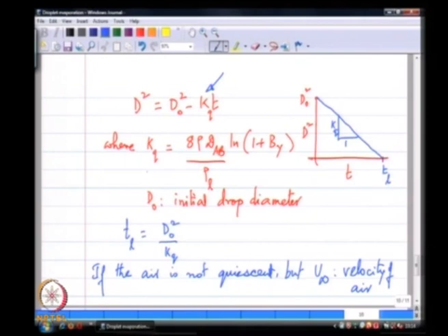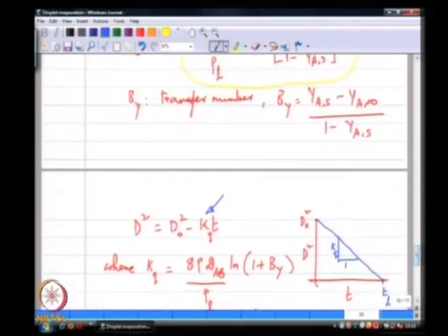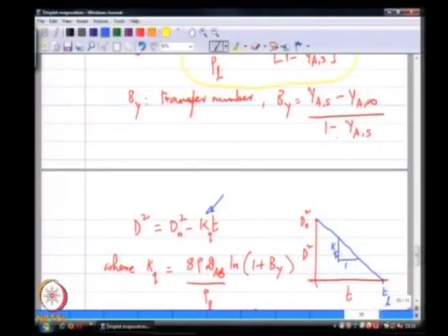There is one point I want to make here, that the difference in the saturation mass fraction versus the mass fraction of water vapor at the infinite condition occurs inside a natural logarithm. So, even if B is very large, since it occurs inside a natural logarithm, its effect is attenuated quite a bit.